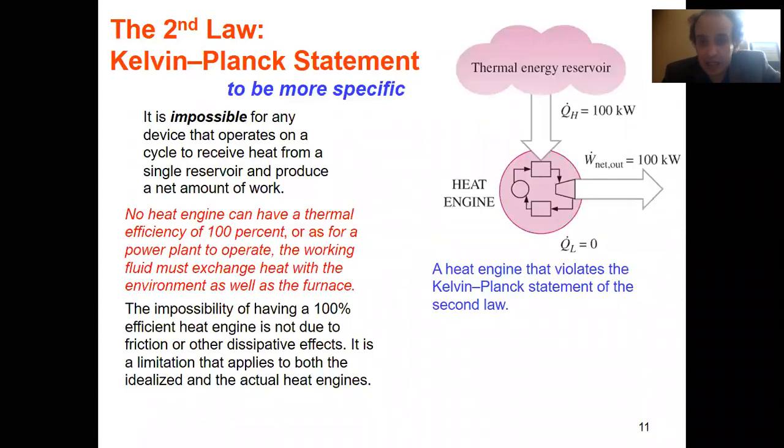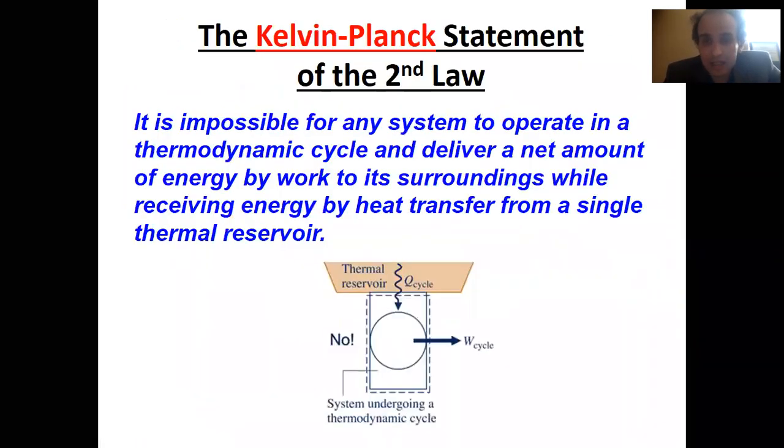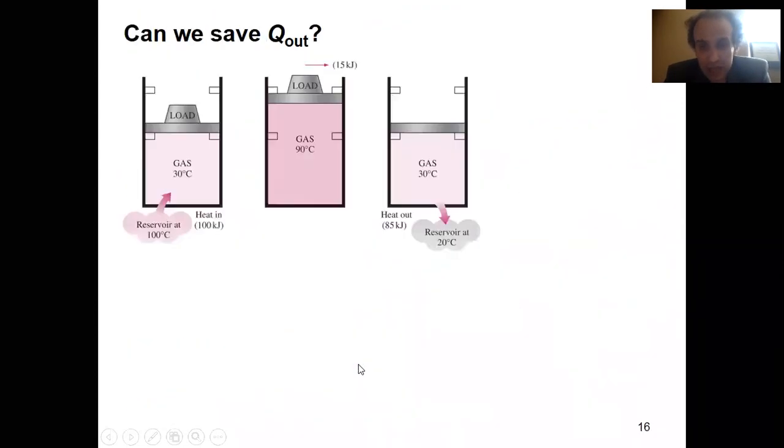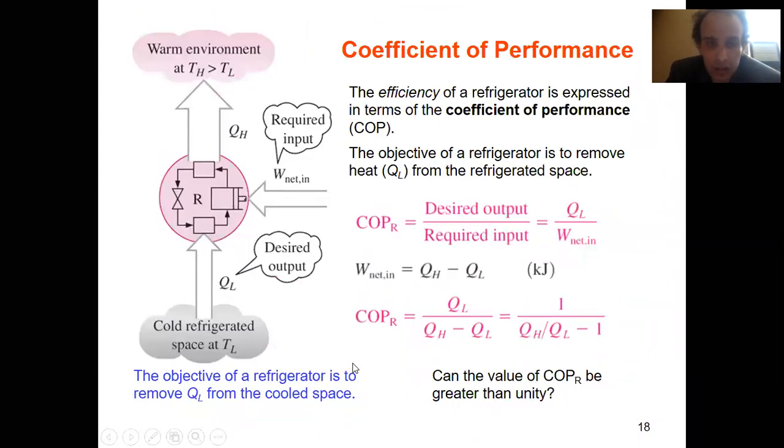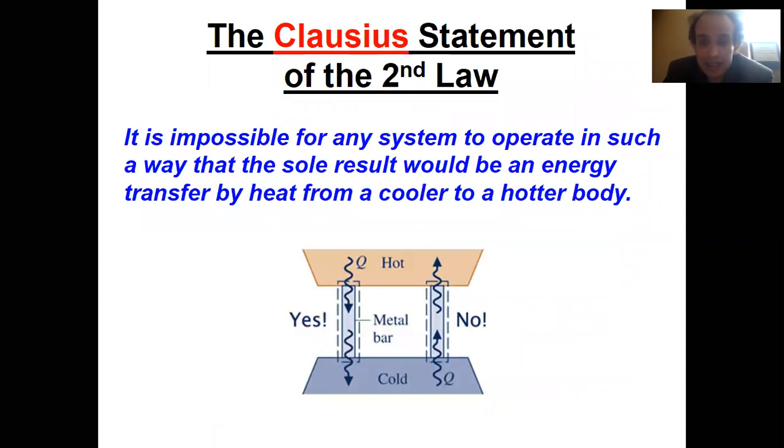And please understand what the Kelvin-Planck statement looks like. It states that a heat engine cannot have 100% efficiency. Why? Because it cannot operate with one thermal reservoir. You should have another thermal reservoir to lose something. And the same for the refrigeration cycle and heat pump cycle, which transfer heat from a cold to a hot source. And there is the Clausius statement, which says that it cannot work for free. You need to deposit some work input to make it feasible. And later we will show that these two statements are equivalent. Either they are violated both, which is impossible, or they hold together, which is true.